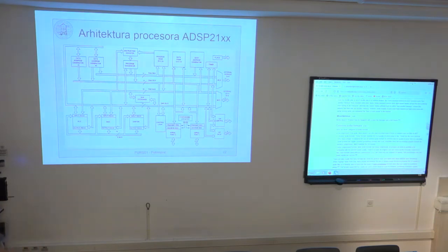The idea is that this load or store either fetches data from data memory and places this data into these input registers of executional units. Simultaneously, executional units use the already fetched data in these registers, perform the ALU operation or MAC operation, find the result, and the result is then stored in this dedicated result register.